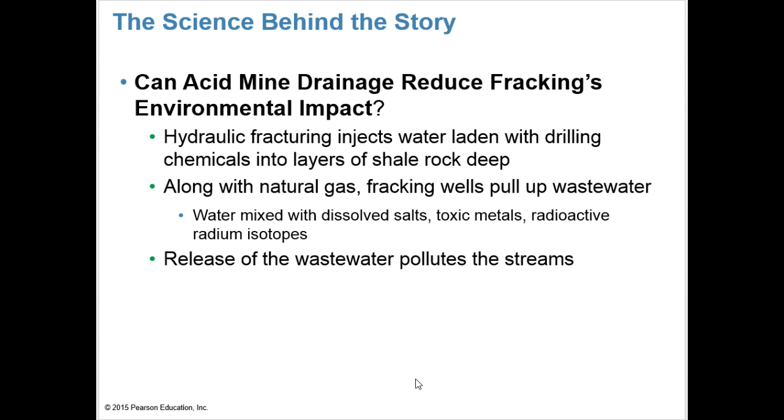The team found that within 10 hours, very high percentages of the barium, strontium, and sulfate, which gives acidic drainage its low pH, and radioactive radium precipitated out of solution. The process was also effective in greatly reducing the salt content of the wastewater. After these reactions, the contaminants from wastewater were concentrated in precipitate, mostly in the form of strontium barite.